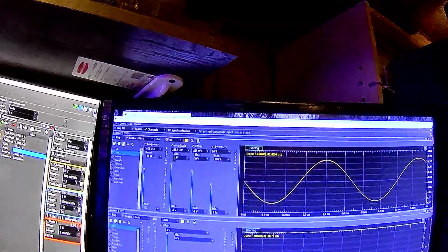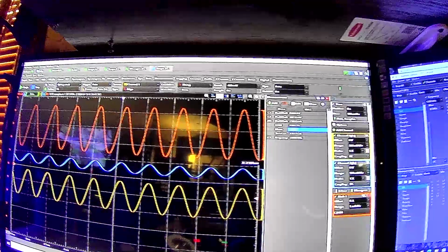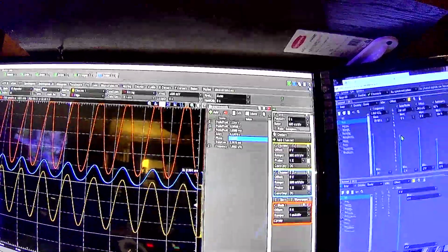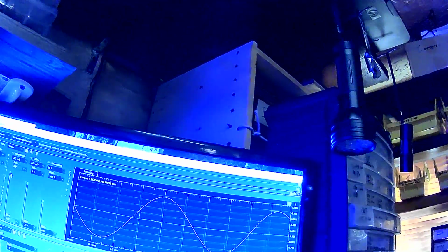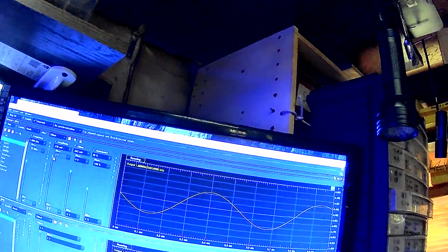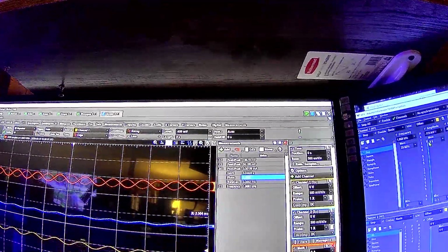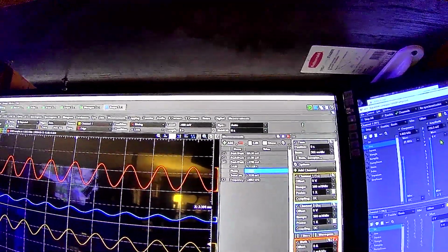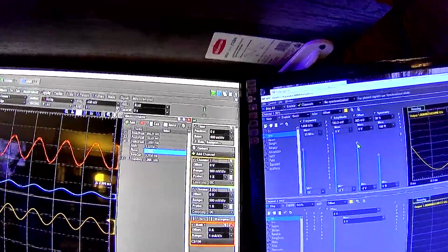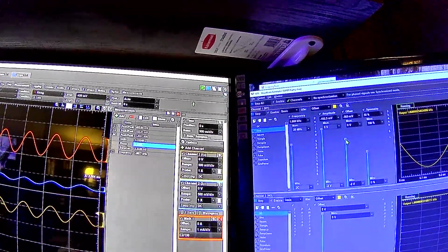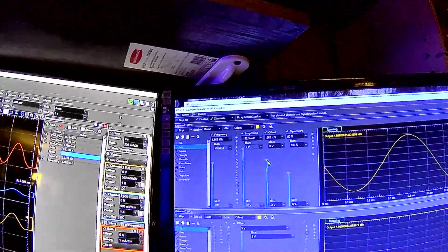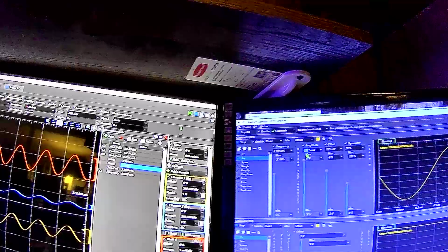Just remember that negative 352 millivolts. So let's see what happens when I change that. Okay, see, that's making my waveform go into the positive area, so you don't want to do that. Yeah, the transconductance is remaining fairly uniform, interestingly. Again, I don't know if that's appropriate or not. I'm not really sure because I'm so confused by my tools here. You should never have tools that fight you. Let's see. Remember, so minus 352, right? Let me set that back to what it was.